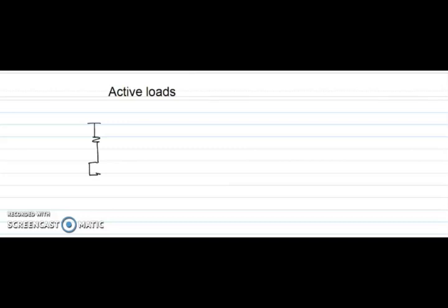So far we would have seen the common source amplifier structure, something like this. We require a bias voltage VB along with the small signal voltage vs. Now we have a resistance R, and the output is taken at the drain terminal, that is your DC voltage VD. We have VDD connected over here. This DC voltage also has a small signal AC voltage, that is capital V0 and small v0. We have current flowing through the MOSFET, that is ID.